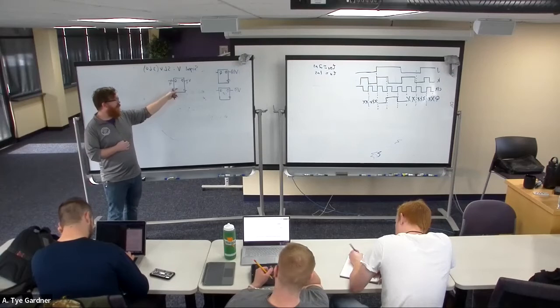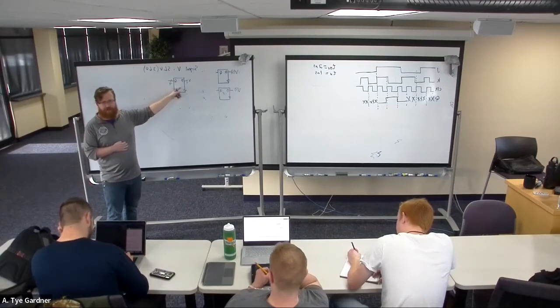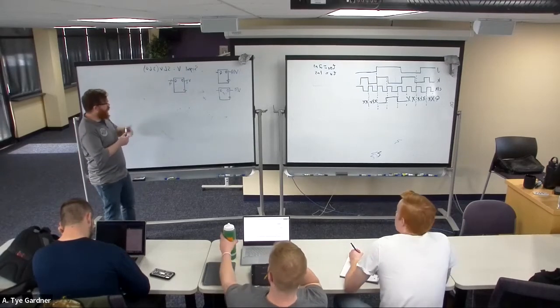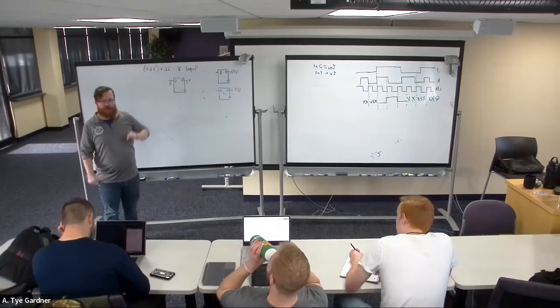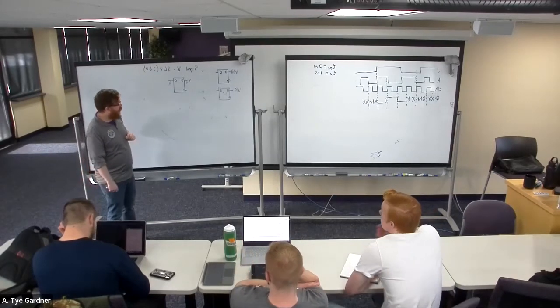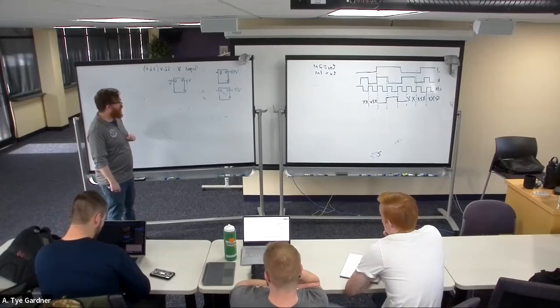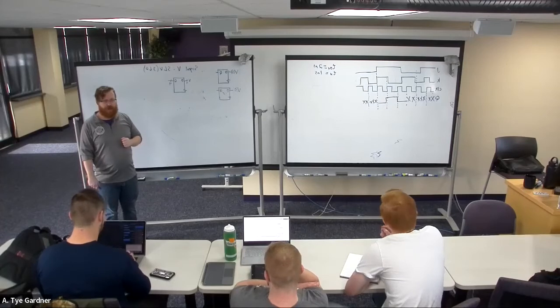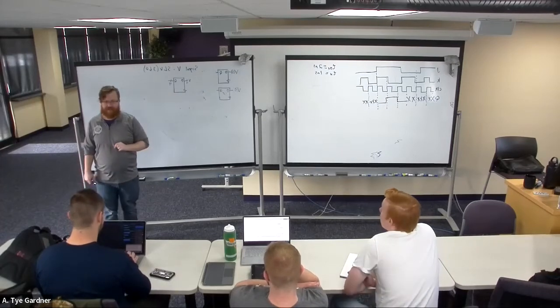I have to understand that inside of this is really 4 D flip-flops, right? And in fact, an exam question, totally valid, would be to draw this picture and nothing else and ask you, what is the minimum number of NOR gates or NAND gates required to design this device?